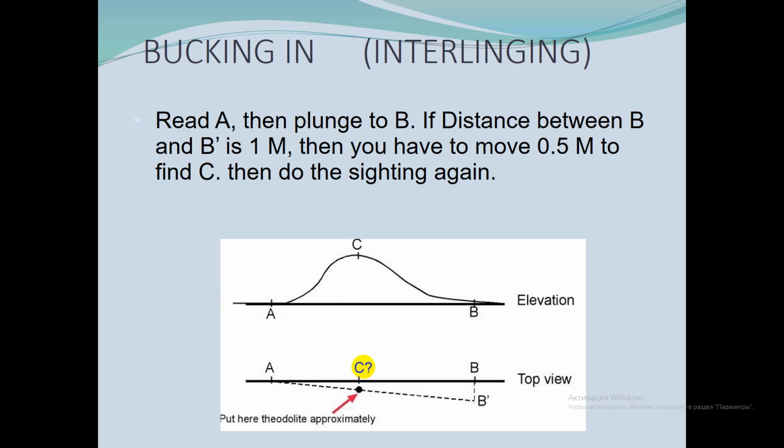It is usually possible to find an intermediate position from which both points can be seen. You can see that points A and B are not intervisible, but point C is in an area from which both A and B can be seen.